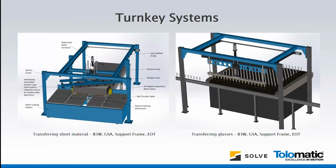So we created a frame between the two jack-shafted X actuators to support the y-axis, and on this y-axis we mounted a turntable that is actuated up and down by a GSA rod actuator. And then at the end of all that is the end of arm tooling, a bunch of suction cups that are going to come in and grab onto those sheets of metal and move them from the ball transfer table, turn them 90 degrees and drop them onto a conveyor. So you can see there's quite a bit involved here, and this is something that can be offered to one of your customers as a full-on turnkey solution.